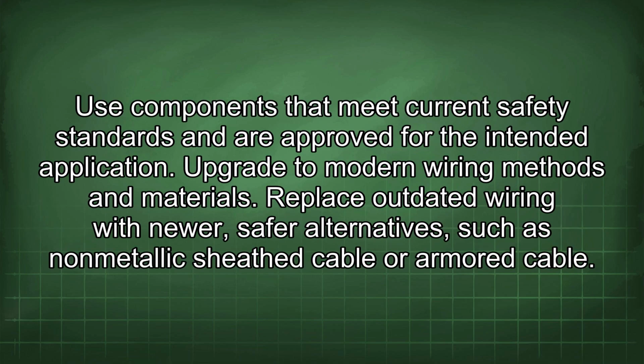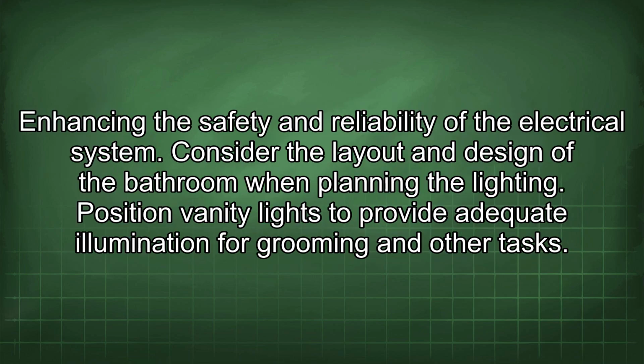Use components that meet current safety standards and are approved for the intended application. Upgrade to modern wiring methods and materials. Replace outdated wiring with newer, safer alternatives such as non-metallic sheath cable or armored cable, enhancing the safety and reliability of the electrical system.